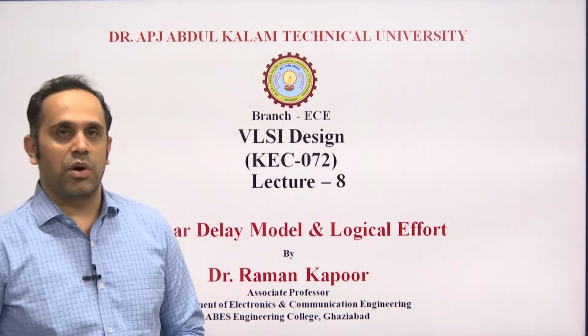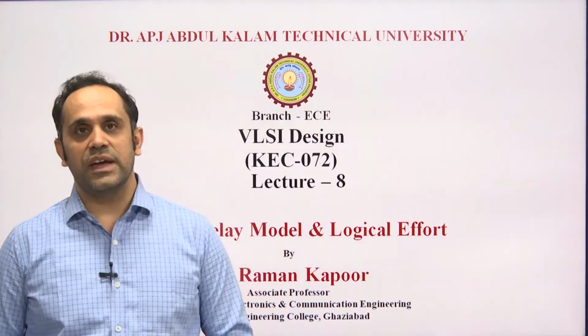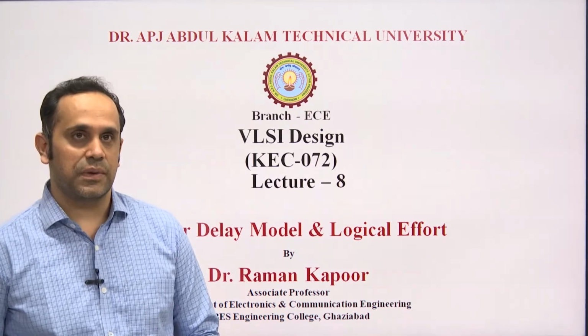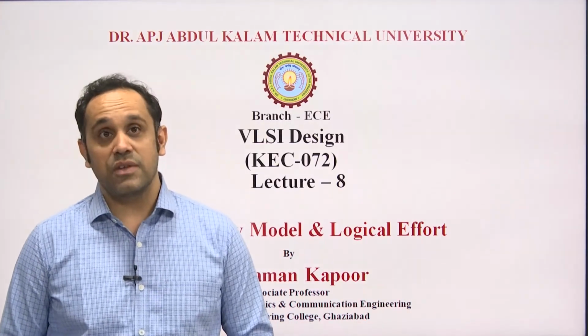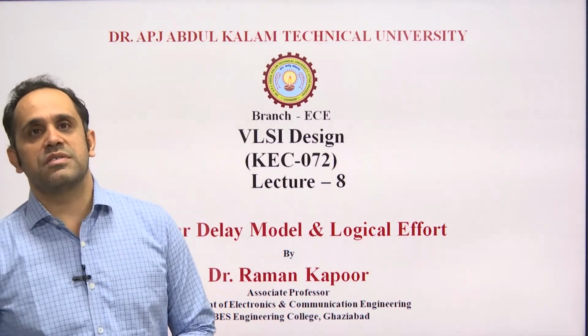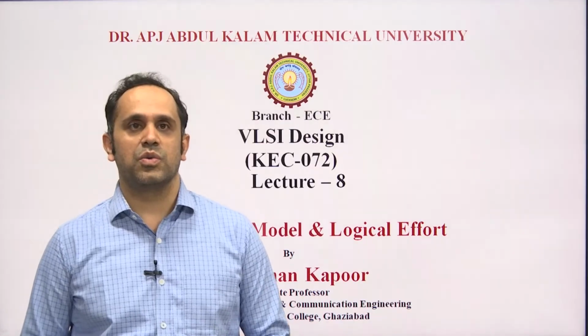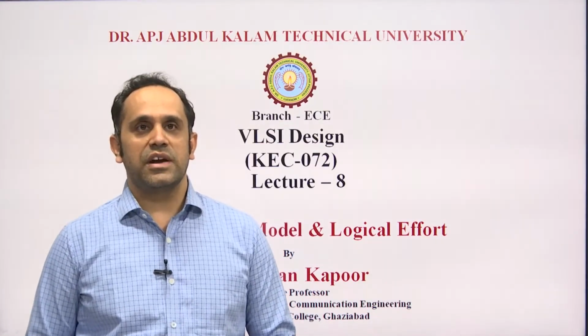So, we will continue with our broad topic which we have been continuing since the last 2 lectures, which is estimation of delay in VLSI logic circuits. Today we are going to discuss another model. We have already discussed the RC delay models in our previous lecture, and today we are going to do what is known as the linear delay model, and will introduce the concept of what is known as logical effort.